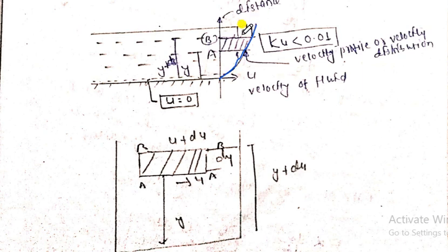increases, because of the cohesion, what you call the viscosity of the material or any fluid, as we go upward it keeps decreasing. So we can say that here at the boundary layer the resisting force is more, and if you go upward then the resisting force slowly decreases, right? So as you can see, this curve is nothing but the velocity profile, or it is also known as velocity distribution curve. So as you know, the velocity at different points is different,